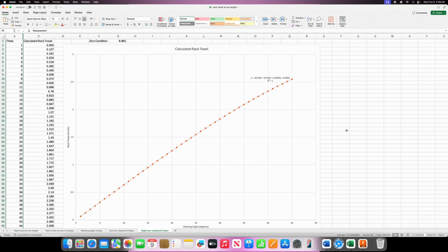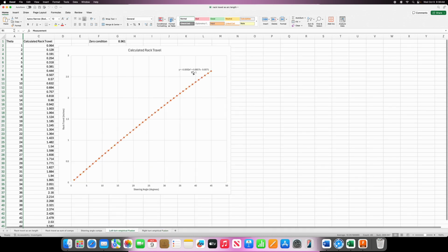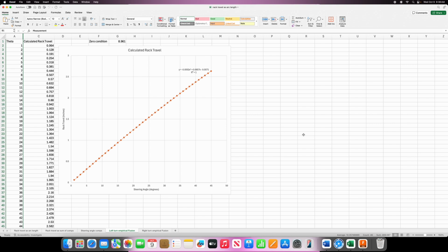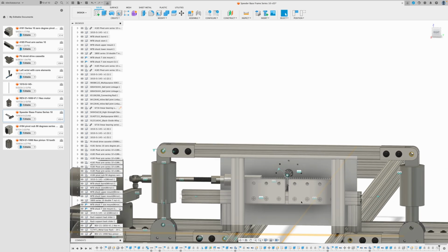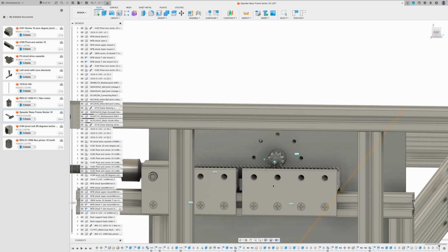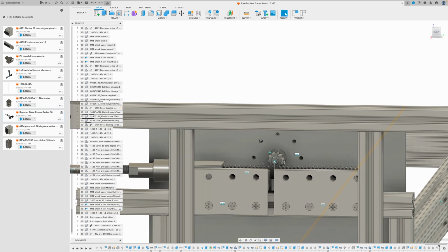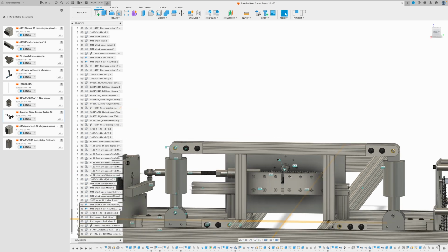So that's basically how the steering system works. You push the stick, it tells the front wheel and the inside wheel where to go based on linear. It calculates the outer wheel angle, and then the two angles for the rear wheels are calculated with these two equations, and that will equate to rack travel. And then with the rack travel, you can calculate how many turns, or what portion of a turn, of the pinion, right? So we've got our little pinion here. Based on that amount of rack travel, how many revolutions or part of a revolution does the pinion make, and that will tell you how much signal to send the motor, or for how long to turn the motor, to make the pinion do that amount of travel. So that is how it's planned to work.